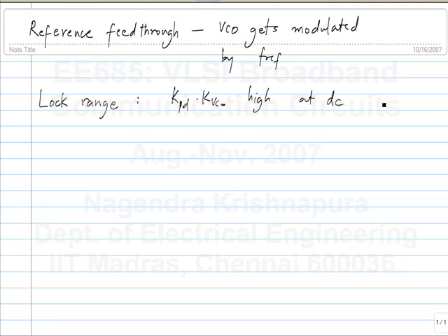So, the control voltage of the VCO needs to be some DC value. So, the phase detector input has to be some DC phase, meaning a constant phase shift over all time. That's what is meant by DC when we talk about phase. That means that the phase difference between the inputs is not changing. So if you have a large value of KPD, then you can have a small value of phase difference which supports a given value of control voltage.